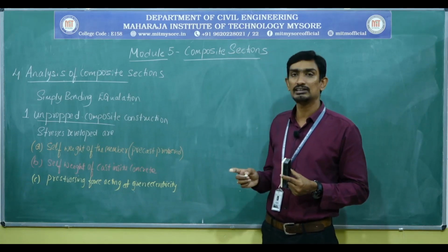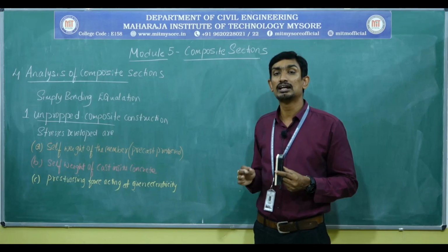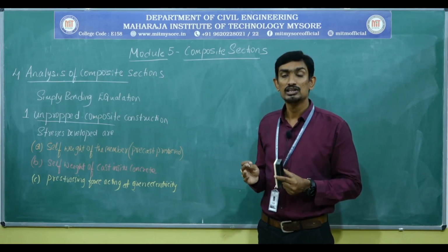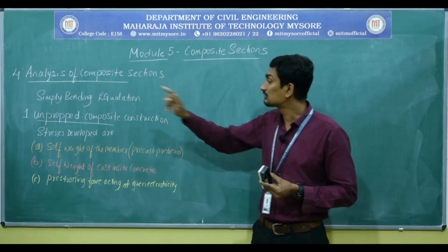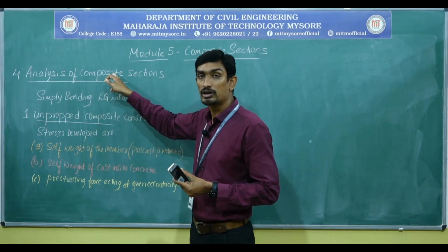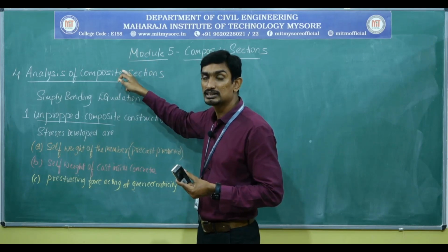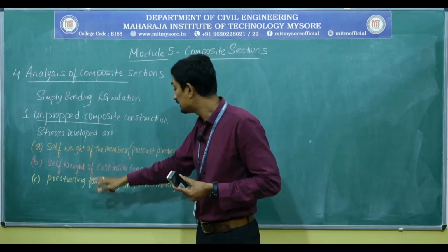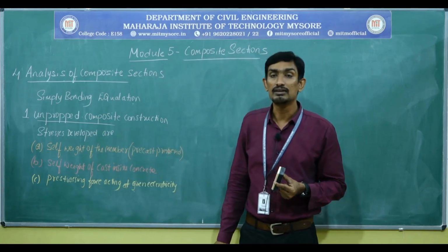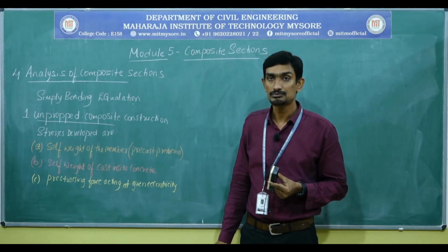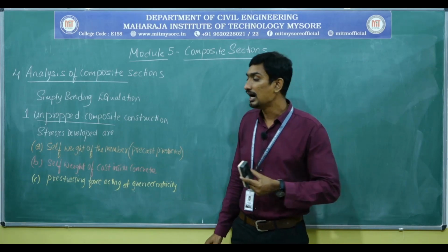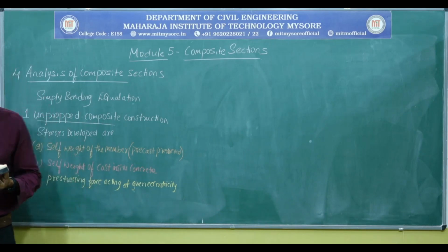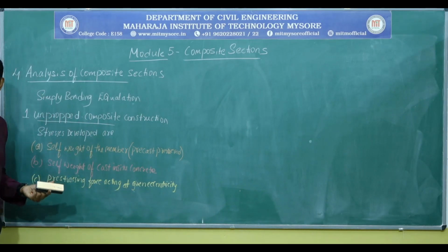So as I stated, analysis means we are going to calculate the stresses. Stresses for what? Stresses for the composite section. Due to what? Due to the self weight, of the cast in situ slab and the pre-stressing force acting at the given eccentricity. Did you get my point? And so this is regarding the casting case.